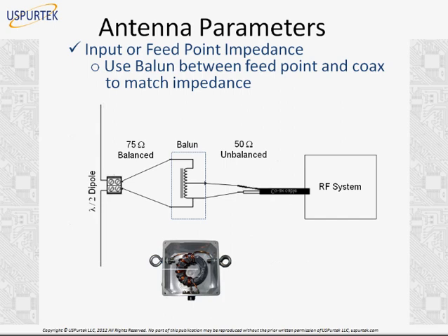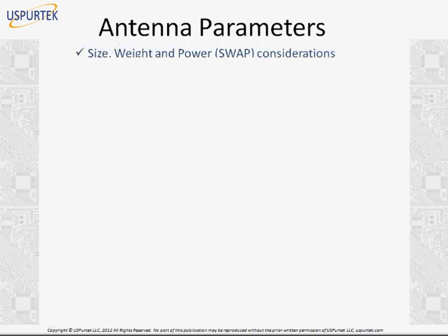the RF equipment. If you own a TV system that connects to an outdoor antenna, you will notice something like a balun connecting between the TV equipment and the antenna system. That is its purpose. It matches the impedance so that maximum power is received from the antenna to the TV receiver. The same principle also applies to all other types of antennas, whether it is a cell tower antenna or a handset antenna or whatever antenna you are using.